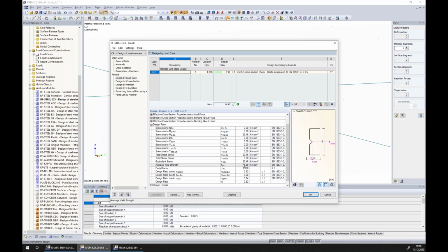And according to this cross-section, the program calculates finally stresses and compares them to the allowed limit stress. And because we know that the cold formed process increases the yield strength by every corner that is maybe pressed into the metal, we can increase the, let's say, average yield strength.